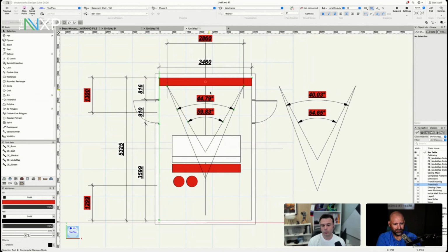So we're close now to being able to define the first pieces of equipment. If we lock in those decisions, which I honestly would not lock them in until we've put speakers and modes in, because we might find a problem and start this whole process again. But if we locked those in, we could now put a projector in and work out throw distance, brightness. We could order a screen at this point because we know how big it's going to be. But after this hour of design, we are still way premature to start putting a projector in the room or ordering a screen. We've got a few more hours of work before we would even be ready to put an order in for a screen.